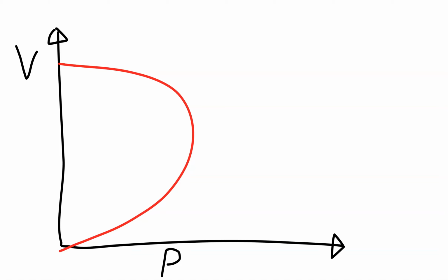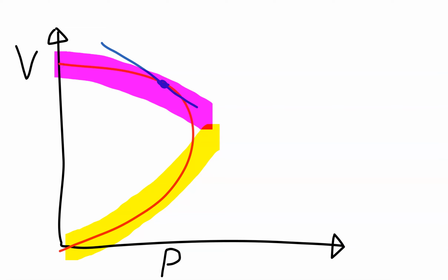So when we're doing the linearization, if you do a load flow problem at this point, we can then have a linearization at this point. Of course, we will come back to that. In this area here, for example, we don't have a feasible solution. We only will have feasible solutions on this side of this curve. This we call the PV curve, but the only point for now is that you understand that this is a nonlinear relationship. That's why we need iterative methods.